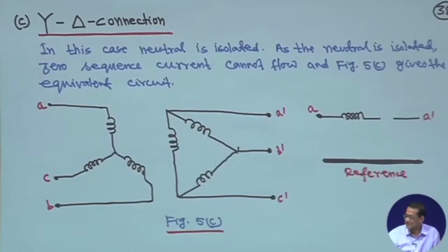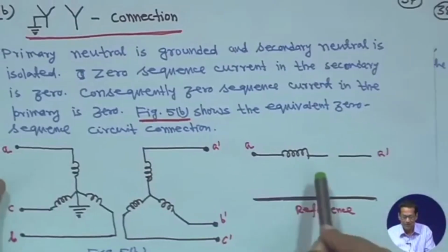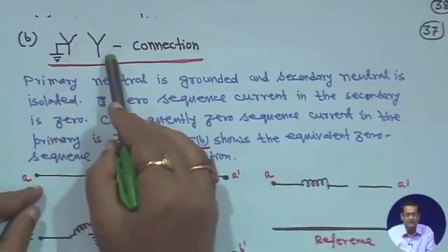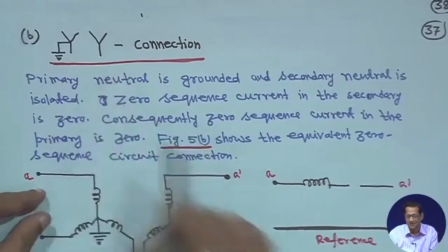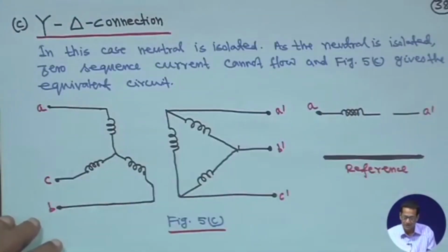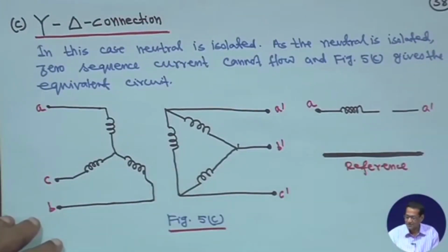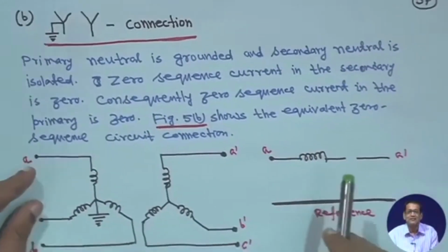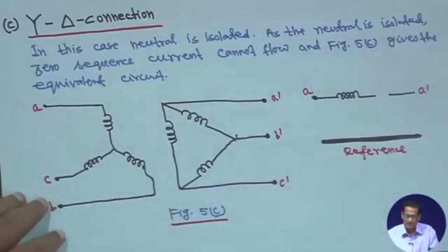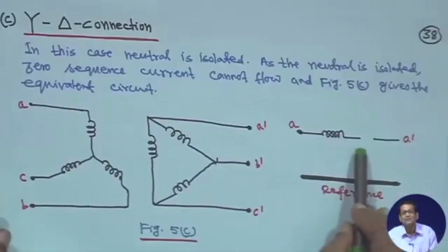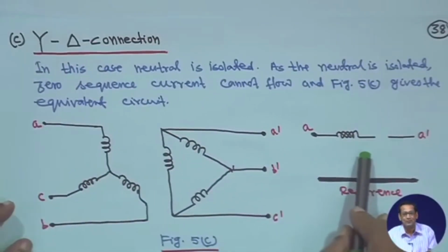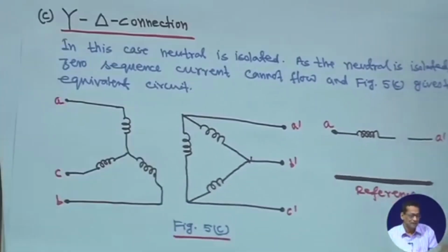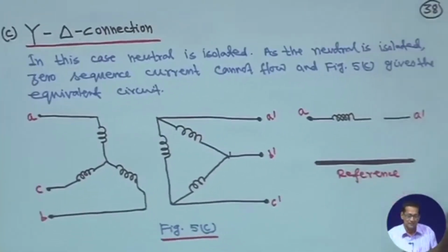That means, of these two diagrams, the star grounded one and the other with the secondary side ungrounded, they have the same negative sequence diagram, this kind of connection, as well as this one. So, this will remain open because no negative sequence current can flow. When we take the numericals for unbalanced faults, at that time we will see how things are connected.